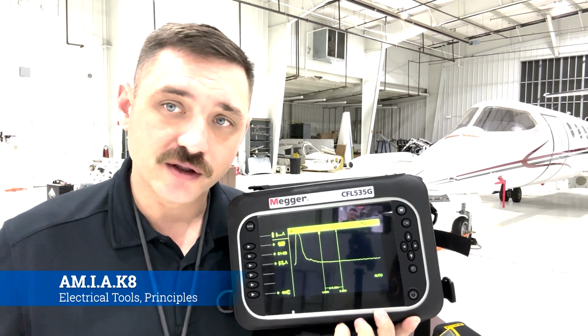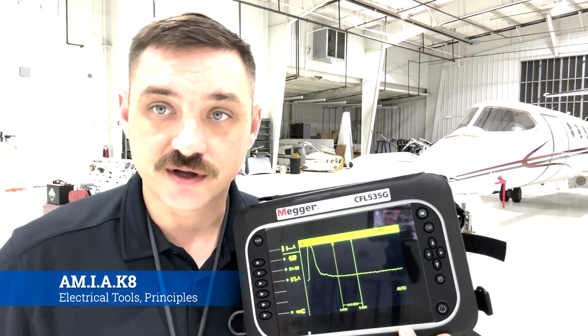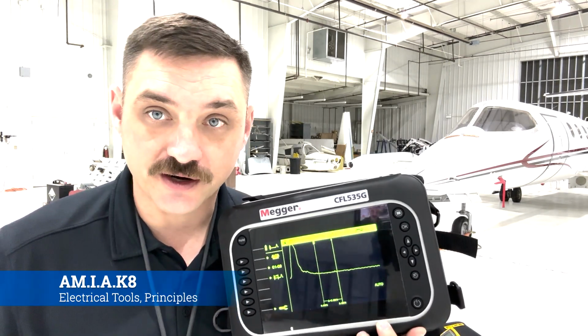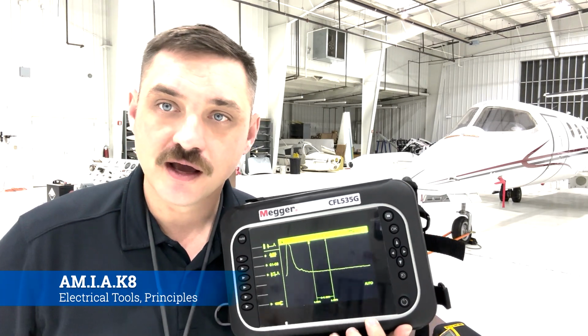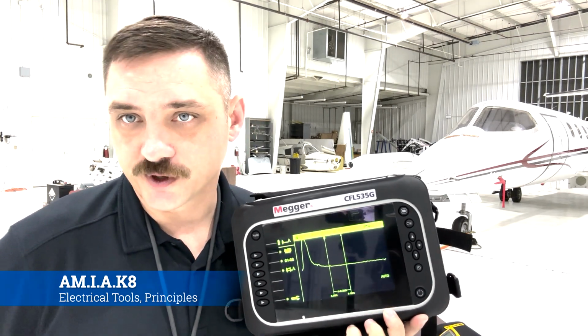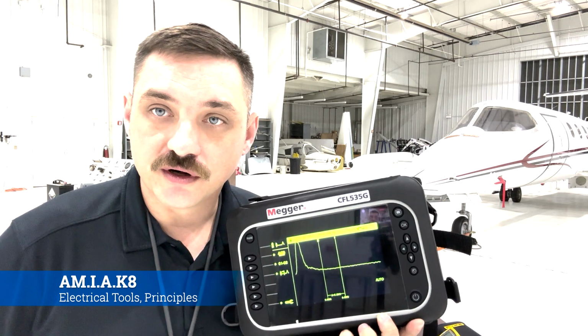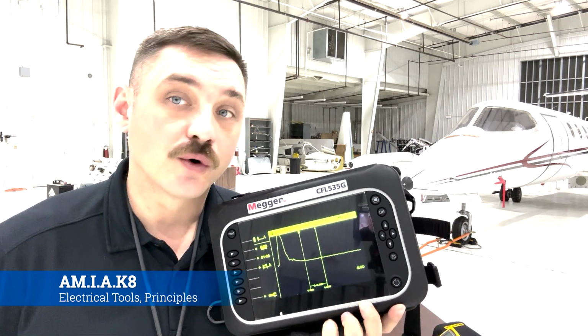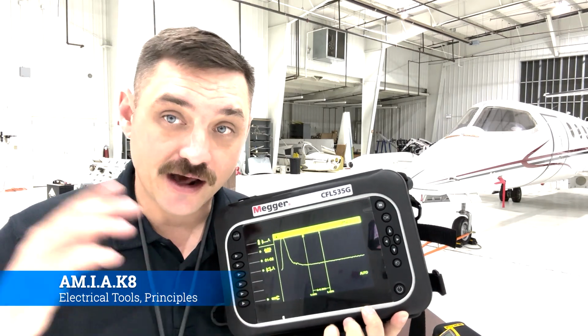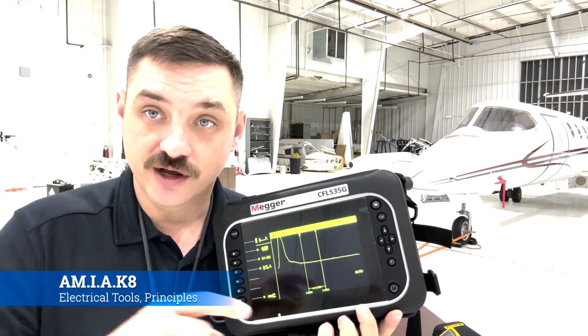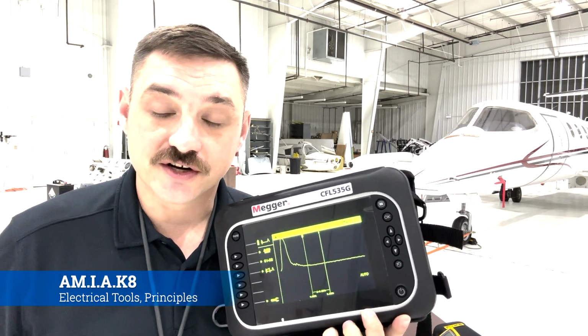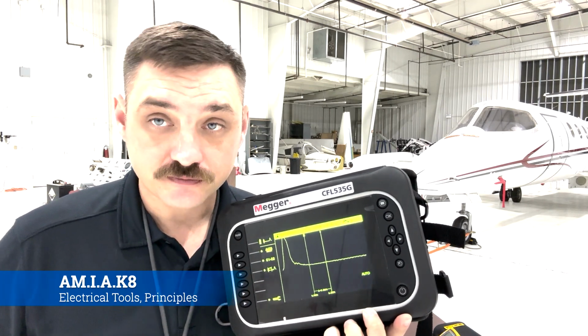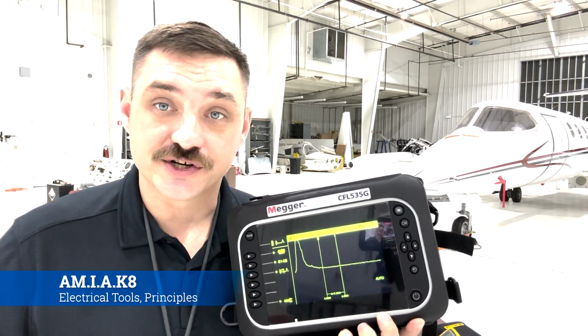Well, for small airplanes, you're right. You can simply open a panel or cock your head sideways and see the end of the plane. But let's say you're working on a 747 and you're up in the cockpit. Do you really want to walk that entire plane to try to find where a wire break is? Or would you rather have an idea of about how long it is, and then go to the manual and figure out a junction to start your troubleshooting there? So a TDR, we're going to show you how to use it.